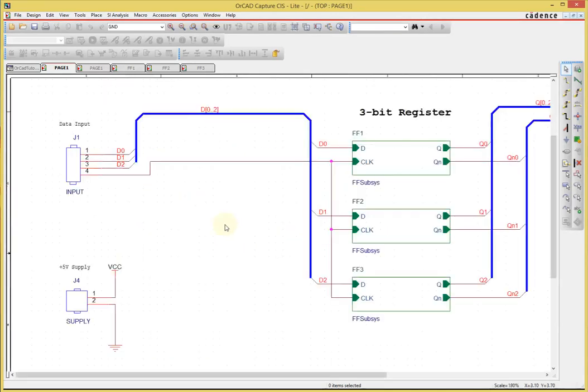In fact, when you hover the mouse over a wire, it will tell you what the net name is. Sometimes for critical key wires, you may want to relabel it so that you can find it on the PCB board when you're doing it instead of having some random name such as N00245.